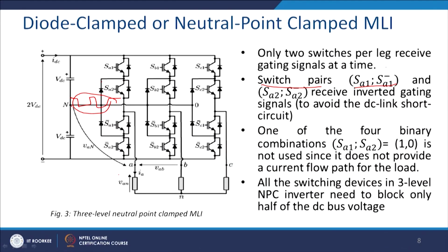So, we have shown on the board previously that the combination of the switches S1 and S2, S3, S4 will be combined in such a way, and we will find some kind of redundancy here. When S1, S2 is on, that is connected with the positive DC bus voltage, then what essentially you get here, you get a voltage VDC. Similarly, when S1 bar and S2 bar is closed, you get minus DC bus voltage, and when S2 and S1 bar is closed, you essentially get a 0.